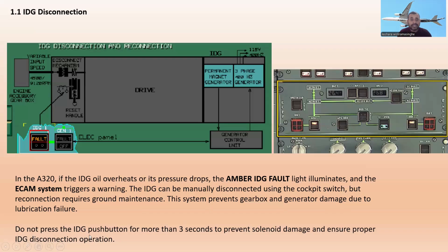Remember, do not press the IDG push button for more than 3 seconds, to prevent solenoid damage and ensure proper IDG disconnect operation.